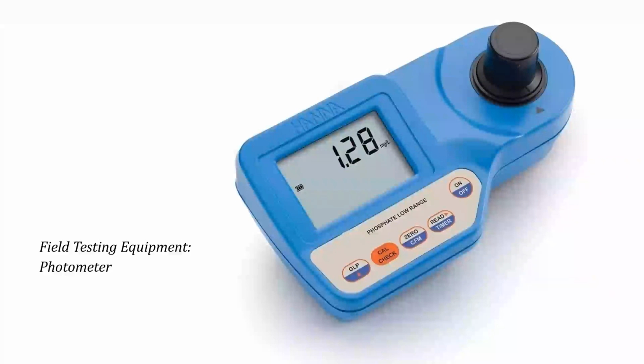For the budget, there's a couple of these really nice photometers that are, I forgot, $500-600 apiece, maybe even less. I can't remember. The Hanna brand, they come in a low range and a high range for phosphorus, and you can get the orthophosphate. You can see the phosphate number here, and they're much more affordable. The key to me is getting data today and using the data today. The data for reporting, of course, needs to be more accurate. And I'm a big fan of letting commercial labs do that, and then have my lab and my operators integrate with that lab to get the here-and-now process control data.